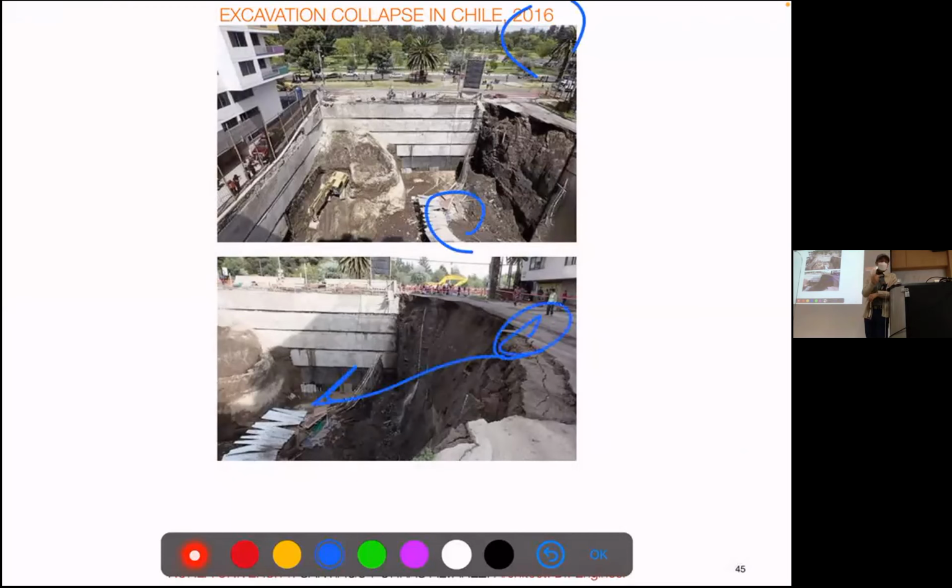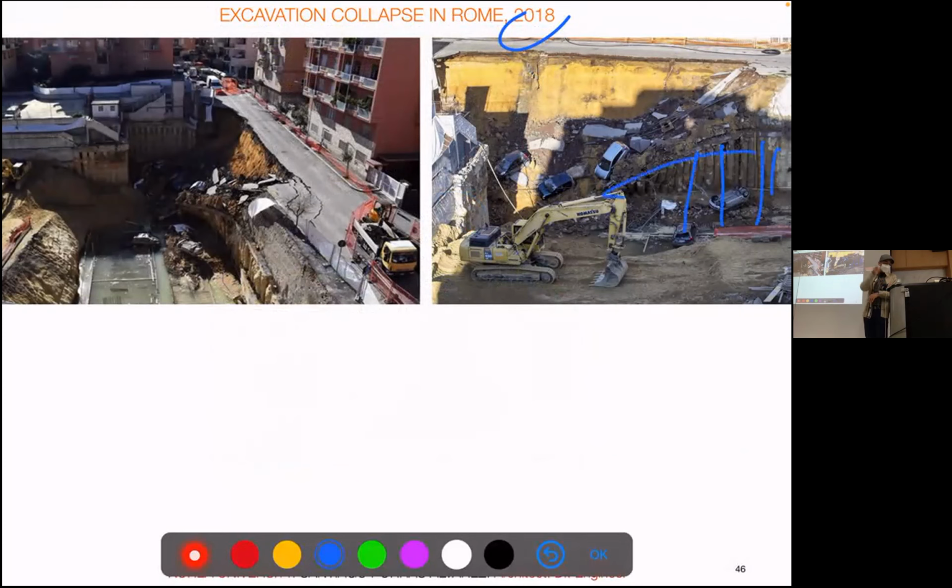And one more, this is 2 years later, this happened in Italy, in Rome. And this is quite correct. It was kind of a set of piles, but they were just the piles themselves. So the concrete was not able to support all that overweight. Maybe with some kind of groundwater, some rain, I don't know the cause, but this is quite embarrassing, especially having built this nearby, because this collapse affects the foundation of those buildings. That capacity affects the ground below that. So this is quite critical. Very careful when you make basements, but especially with nearby buildings or with the streets.